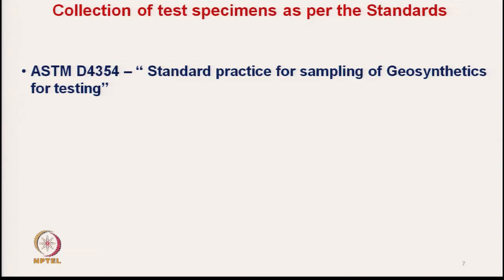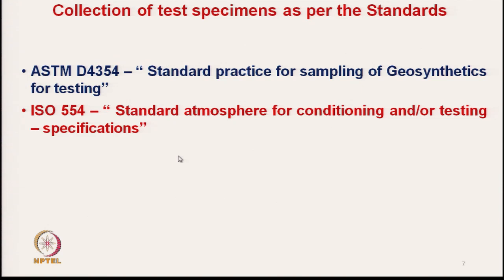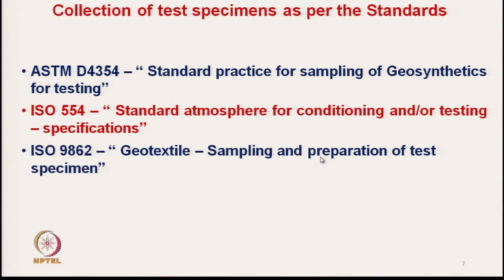Now, there are standards for collection of test specimens. These standards are ASTM D 4354, which is the standard practice for sampling of geosynthetics for testing. Then ISO 554, which specifies the standard atmosphere for conditioning and/or testing specifications. And ISO 9862, geotextile sampling and preparation of test specimen.